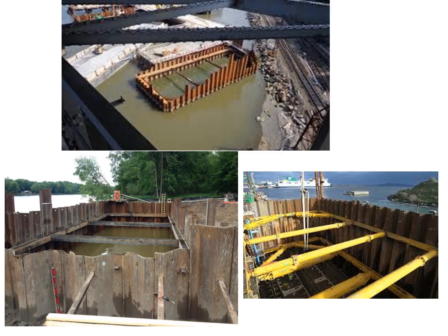So these are some of the actual pictures. Here you can see a single layer of sheet piles. These are struts. Here also you can clearly see in this figure, this is the sheet pile. Sheet pile is nothing but, as you have learned in pile foundation, a non-load bearing pile which is driven vertically in the soil or riverbed, and these are wales, and these are struts, wales and sheet pile.